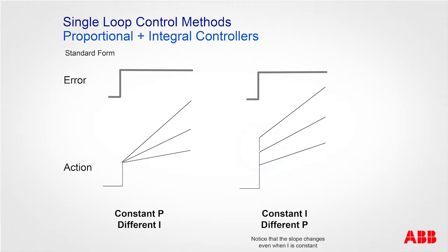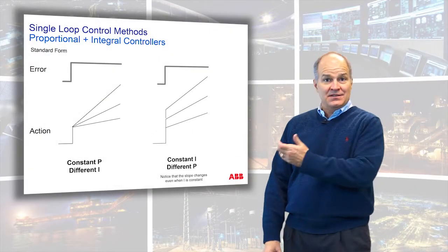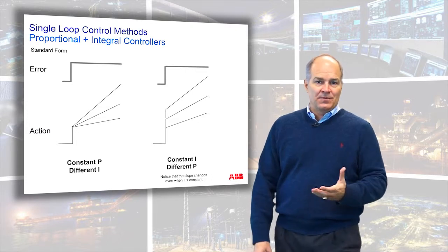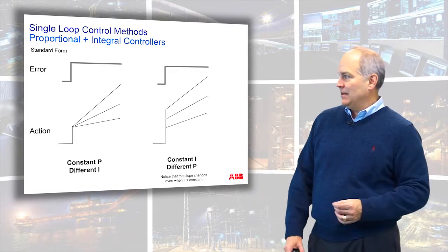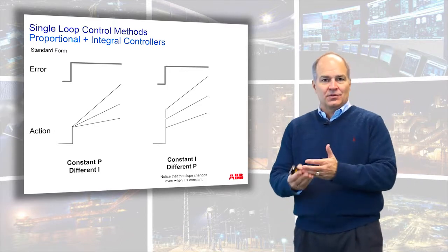So what I see here is in the first step it's proportional, then that's proportional, and so the way you look at it is if you could draw a line, how long does it take for this integral time to add up to this? Well, that's how long it takes. So the integral time, the effective integral time is the same. That's called the standard form of the PID algorithm, and we'll look at that in more detail. But this is showing how the proportional and integral work together.